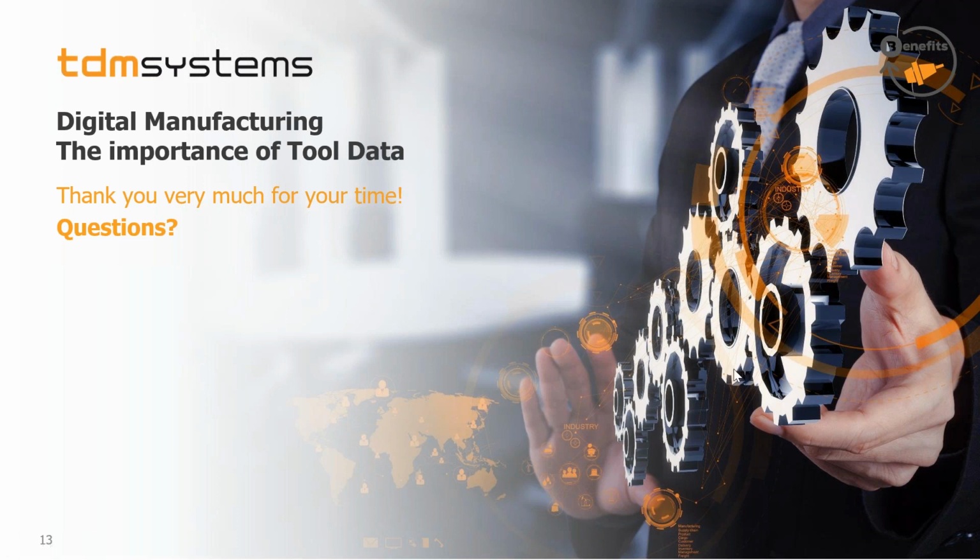Let me click on it. The question is, can you monitor in any given time which tool is in which machine? So the question is basically, if you remember the last tab in the live demo, can we monitor tools in a machine with their tool life? And the short answer is yes, of course. We can monitor every tool in every machine at any given time. We know where the tool is. We know even a serial number of a tool. If it's a Duplo tool, we know the tool life, the remaining tool life. We can compare the remaining tool life with a warning limit and make sure that we bring the tools to the machine before the end of their tool life.